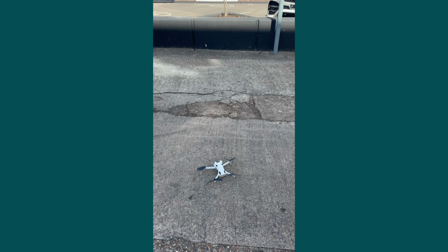So here today we're going to use the DJI Mini 4 Pro to capture the building outline of a building we want to fly, and after we've captured that building outline, we'll generate a 3D mapping mission to fly around the roof of the building and capture the roof area as well as the facade. After doing that, we'll take that data and those images into Hammer missions in order to generate a 3D model.